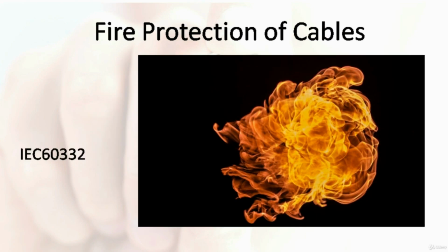For both the data and electrical cables, PVC or polyvinyl chloride and PE, or polyethylene, are the most common insulating jackets being used. These jackets are combustible and have a probability for propagation of a fire, and this is more prominent when the cables are bundled together. Now, fire protection of the cables in your mining farm is really not a must-have, but it's good to keep it in the back of your mind when you are choosing cables for your mining facility.